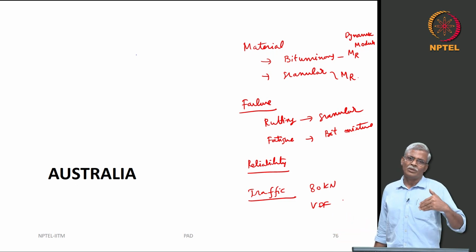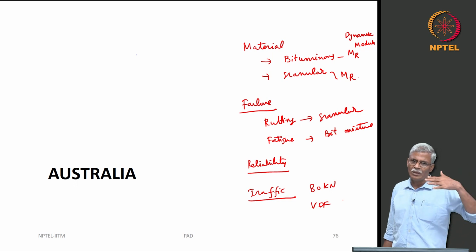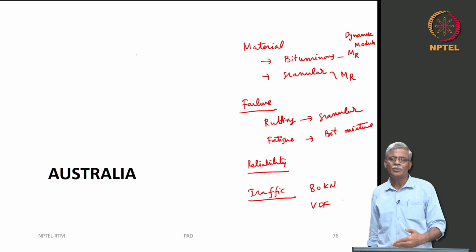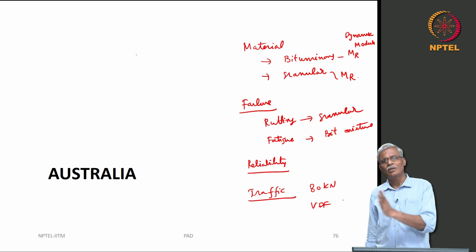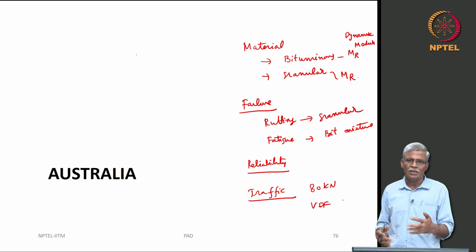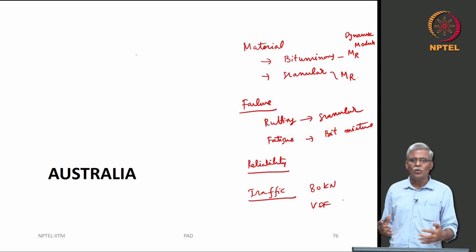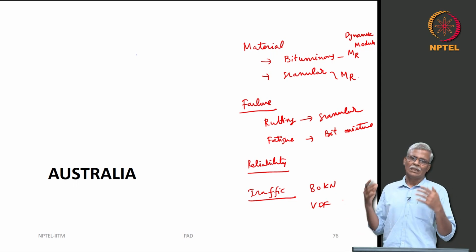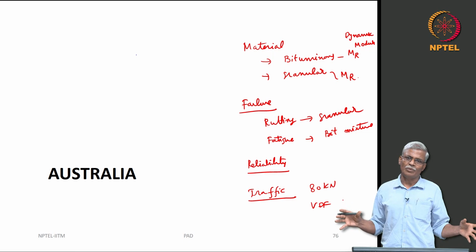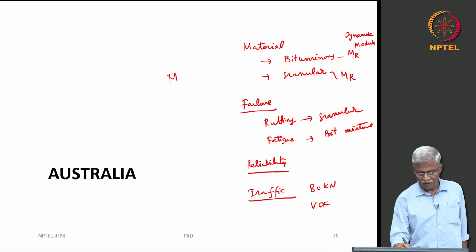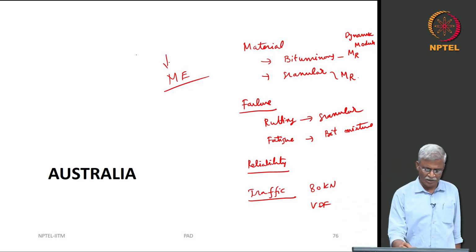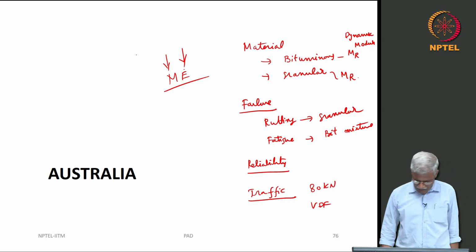So, the South African method will score in terms of having detailed procedures for each and every one of these steps. The Australian method will be different in it, and my idea, especially for the students here, is to make you understand how the same pavement cross section is designed by different countries in a completely different method, but all of them will say that they are mechanistic empirical. And we know what is the mechanistic part, we also know what is the empirical part.